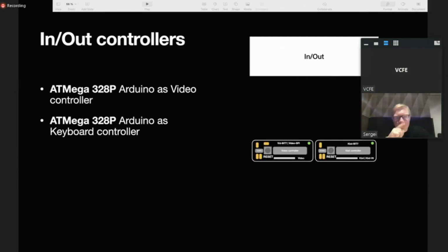Regarding controllers, it's just Arduinos using classical code to work with the video controller, but we needed to speed it up. We used the basic driver for such displays, but we needed to put everything in one file and speed up this SPI connection to speed up the scrolling, because basic scrolling wasn't very fast, and we needed to work on this because otherwise it looked really strange.